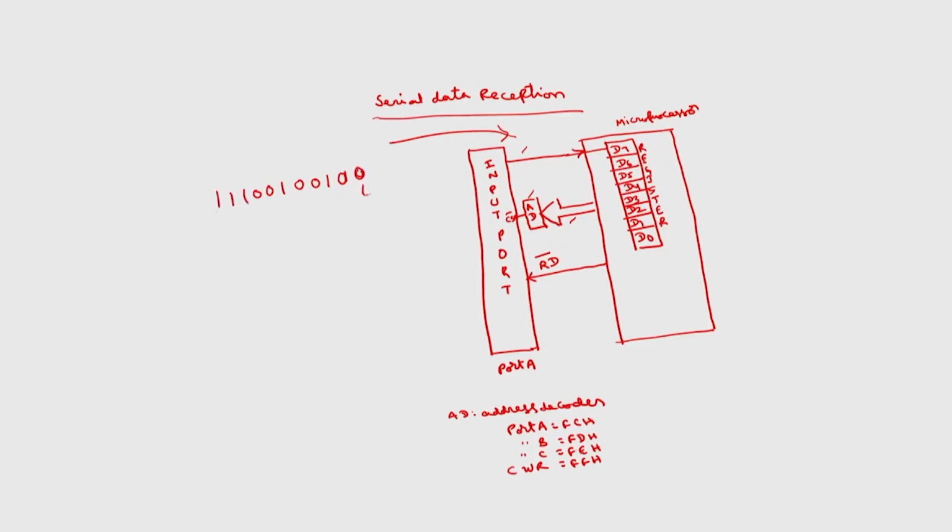So, this is the start bit. First the start bit will be received, then the character will be received. The character is 4 and 9, then 2 stop bits will be received. Whatever data is received on the input line of port A, I will take into some register. Say I want to take this value into register AL or BL. So, what will be the program for this?